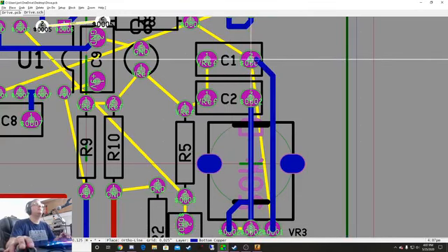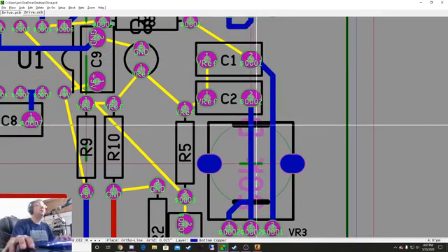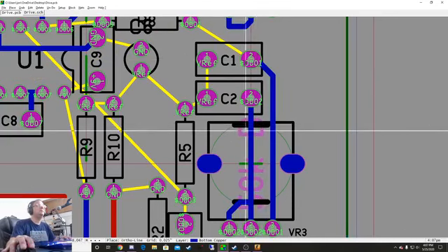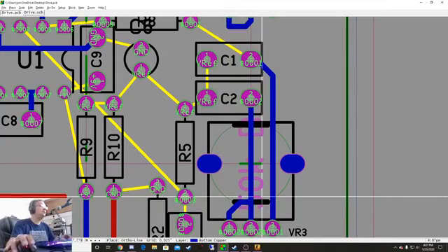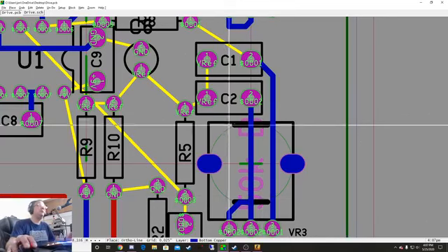Now, something to notice here, these black lines are showing me where the little standoffs on the pot are, and those are metal on these particular pots. So if I'm doing top copper, I avoid these lines because I don't want those to sit on top of the copper, and then if the masking has a flaw in it, you can short the trace to ground right there.